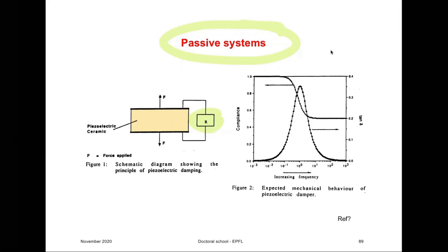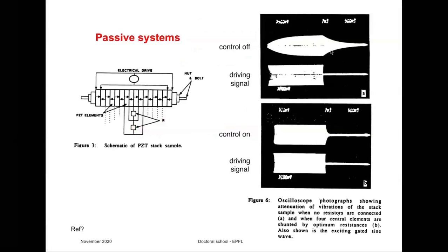So what you do, you put a piezoelectric element in a vibrating structure. The structure vibrates, the piezoelectric vibrates, and then if you have this shunt resistor, the part of that energy which is transformed from the mechanical energy into piezoelectric will be removed through heat, because basically you are producing current, and current will produce heat. This works. You can make very elaborate structures.